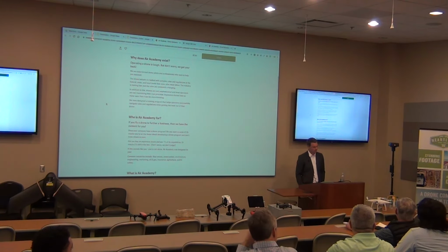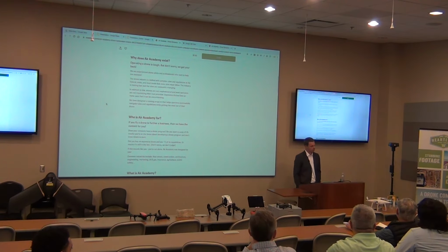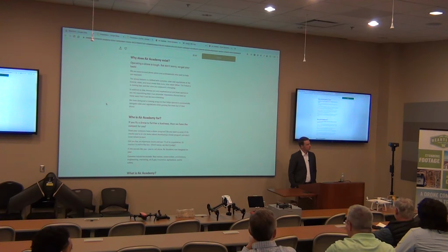And you've just done that procedure that you described, where you've taken the site plans, converted it into a GPS coordinate on a known site that's already been surveyed by the drone, taking into account whatever work's been done, and throw your geological survey or your county plat out the window at that point, and you'd rely on that drone GPS data. This is a good one, guys.